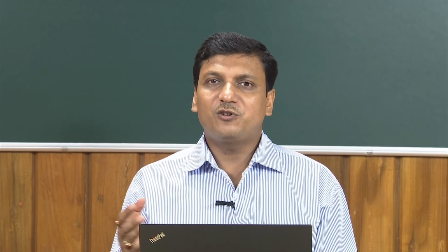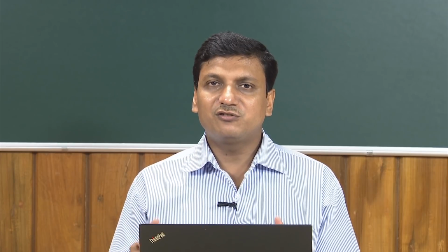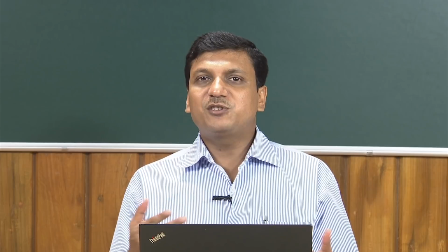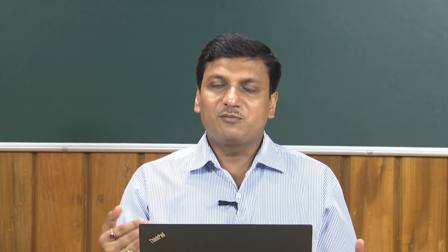After doing the welding experiment, we cut the sample, polish it, and then etch it, and we are able to find the weld dimension for a specific welding process parameter. If we simulate those welding process parameters, we will get almost similar results. If you do a very good simulation, we will be able to represent the welding condition.